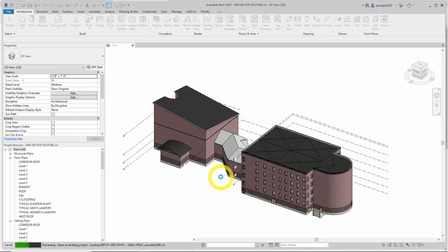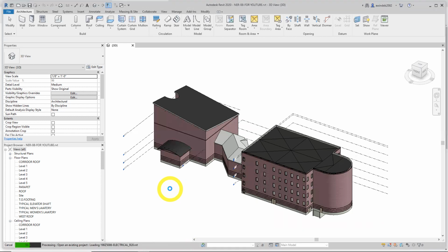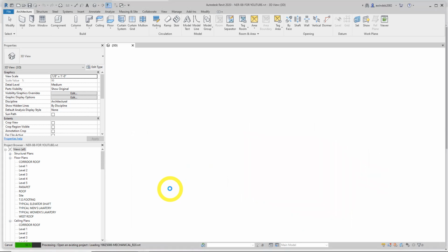So one of the first things we do is we make a grid for our structural items. Structural engineering, one of the most important starting points is certainly the grid. They're essentially placed one line at a time in Revit, but we make quick work and copy and move them over as we're going to do here in this first part of this chapter.